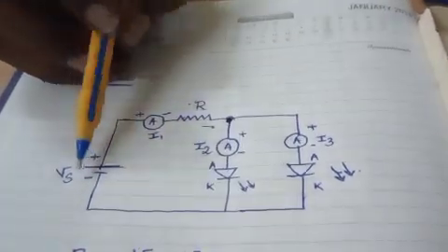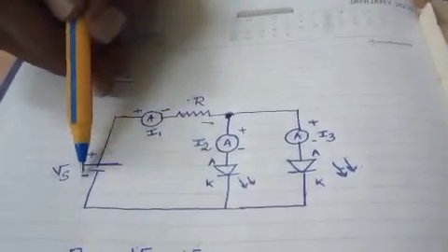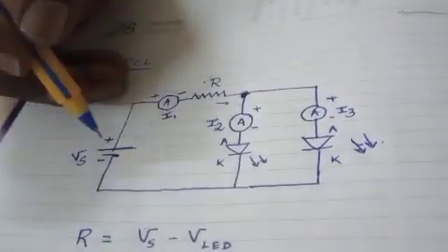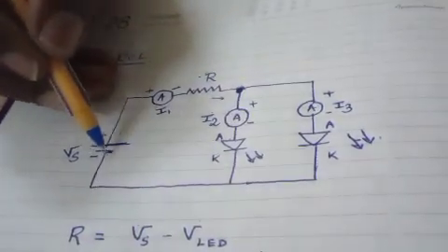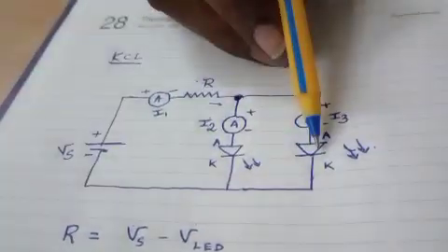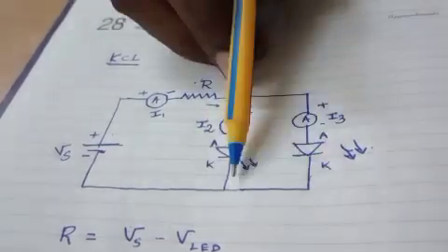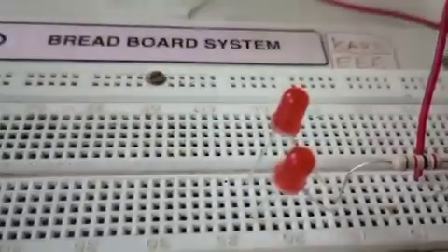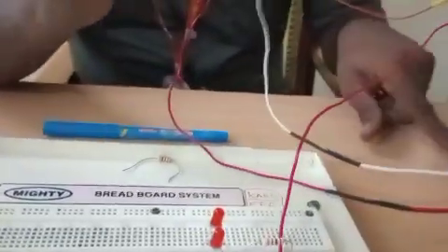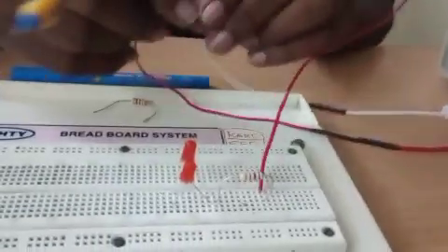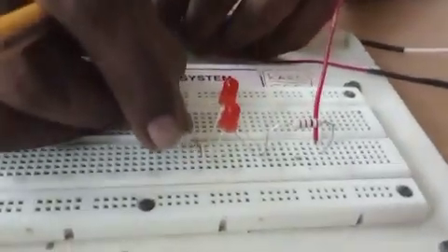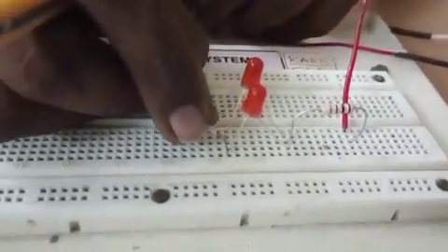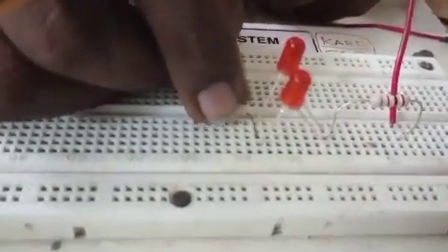Okay, now next see, we need to connect the voltmeter. So let us connect the negative end of the RPS with the cathode terminal of these two diodes. You can see in this board we already connected the cathode terminal on this common point, right? This is the negative end of RPS, see black color, negative end of RPS. This I will connect with the cathode common point, right? This is the cathode common point, so I will put it over here.